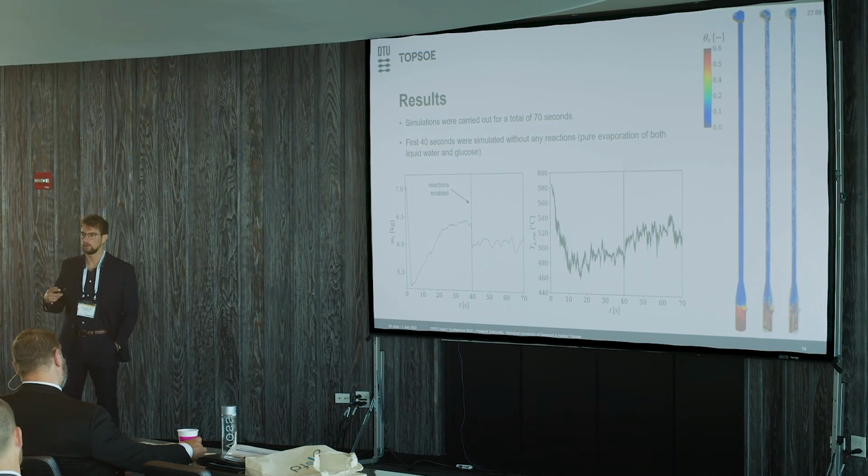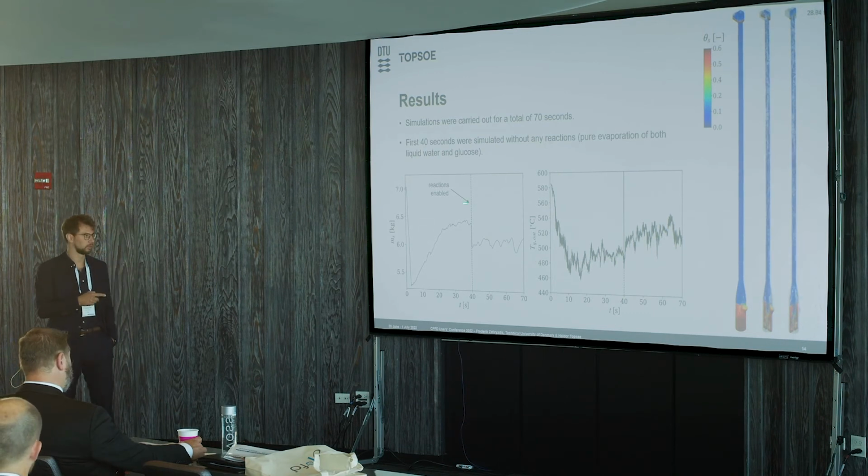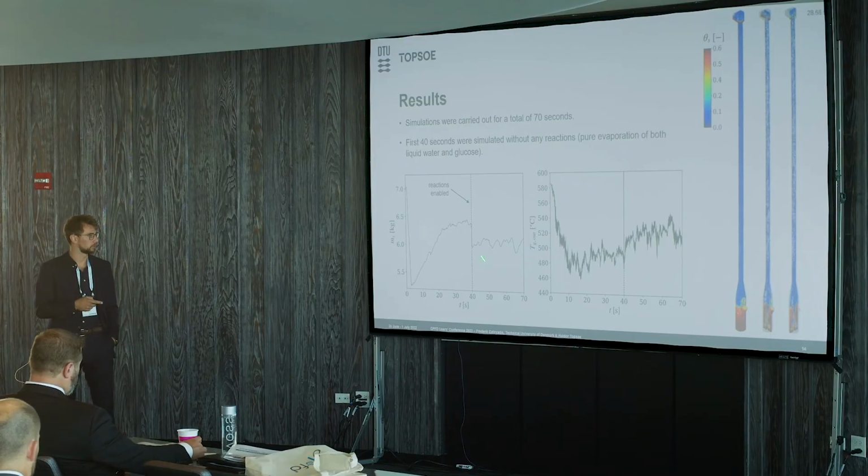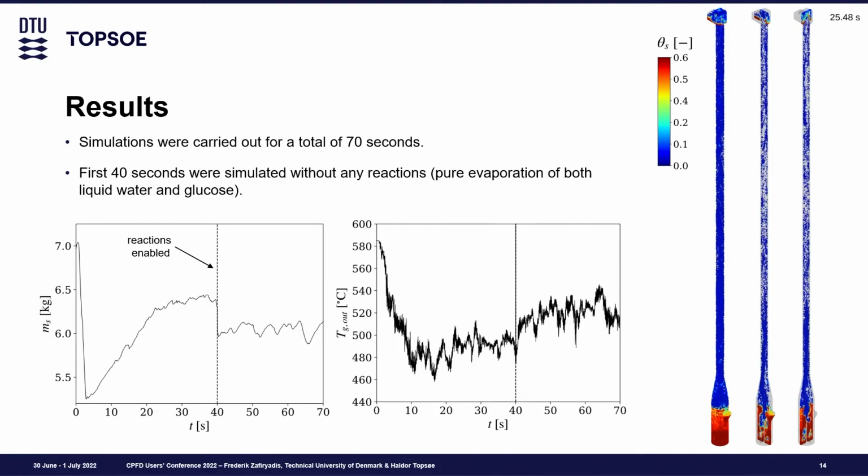We have a constant flow of solids going into the system, so naturally the bed mass inventory is bound to change depending on whatever drag model you have, depending on the operating conditions of your nozzle. But that is actually quite good at finding a steady state level here. We also see quite a difference between just having 100% evaporation and having the reactions in place. That actually makes a difference there. So it's not equally endothermic, the two reactions, whether you're considering cracking compared to pure evaporation.